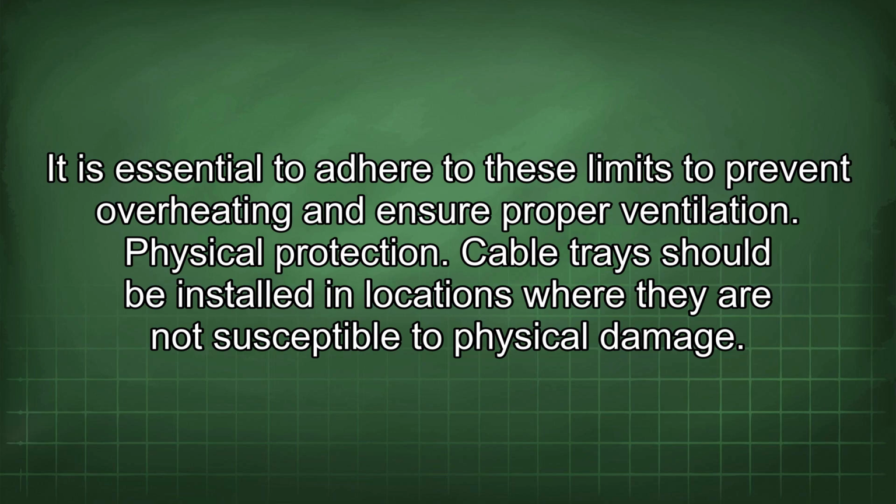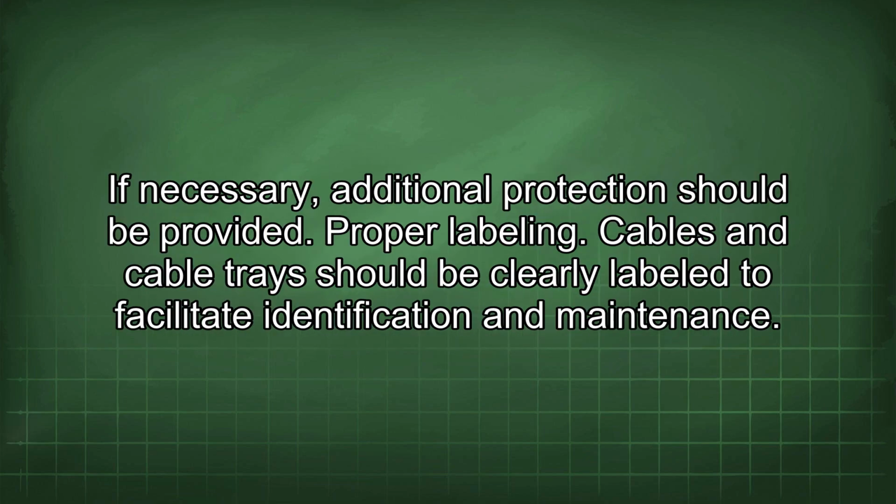Physical protection. Cable trays should be installed in locations where they are not susceptible to physical damage. If necessary, additional protection should be provided. Proper labeling. Cables and cable trays should be clearly labeled to facilitate identification and maintenance.